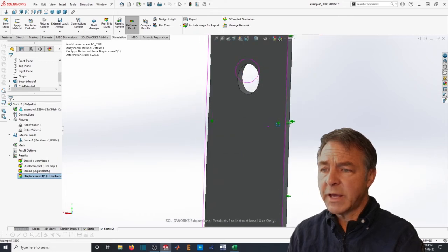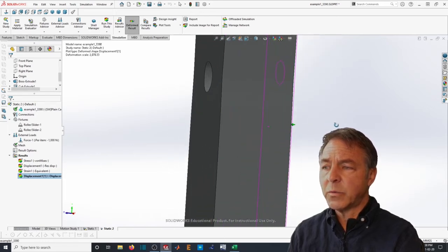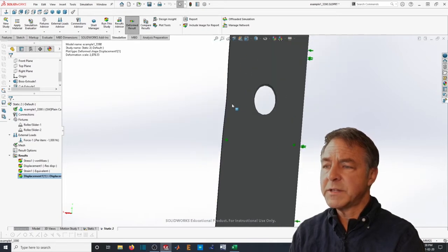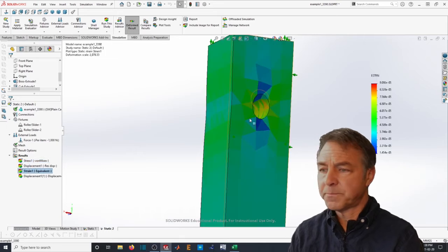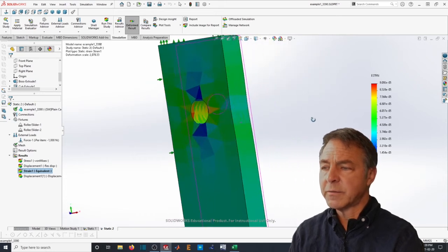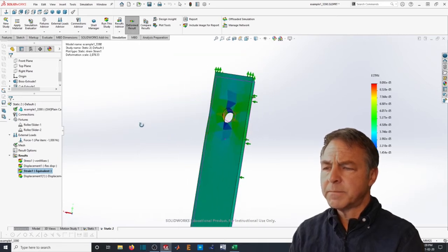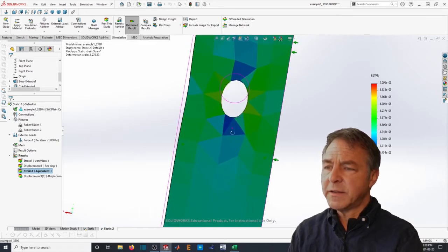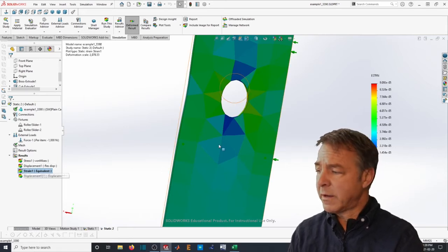and you can see that we have quite a different behavior here. Now, what's curious about this is we've got this necking down of the model. Let's look at the strain. We've got this necking down on one side, but not so much on the other. And there are these features here. Those look a bit odd. Now, the other thing that's happened is that the hole that we drilled, a circle, has stretched. And that's rather strange.